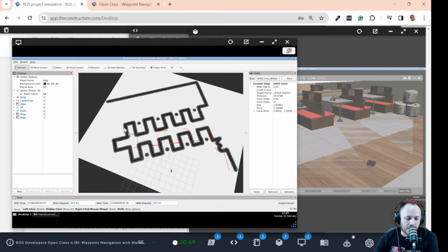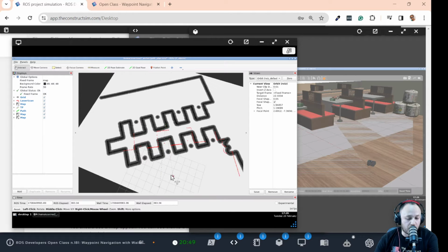And as you can see, right now the laser readings are not fitting the map. You can see there is a small error here. But this is normal, okay? Why? Because the position that I have provided is not super accurate. However, if my localization system is working properly, as I move the robot around, this should get automatically corrected. This is a small error.